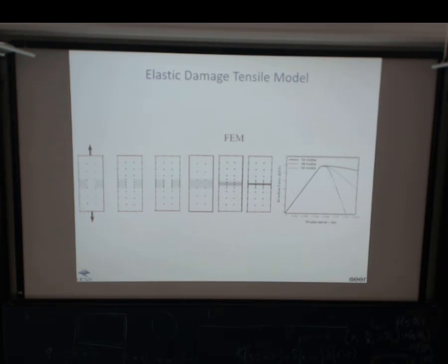And here's an example. I take a very simple elasticity problem, but assuming that beyond a certain stress level, the material is damaged. So I take the sample like this, introduce an imperfection. As you load it, the stress is not going to be uniform, but there will be some concentration right here. I have small imperfections, so that the damage initiates from here.